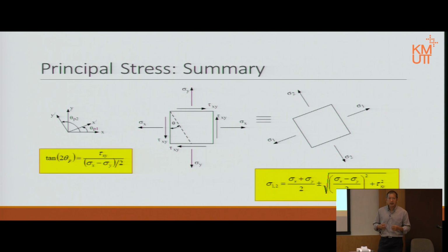And as I said, minimum in terms of mathematics means negative is always smaller than positive. In the engineering sense, it's not. In the engineering sense, negative means just changing direction. So we also need to find the minimum value as well. And therefore, we concern ourselves with the maximum and minimum principal stress, as we indicate here. And of course, on these planes, where we have sigma 1, the maximum principal stress, and the minimum principal stress, the shear stresses are 0 here.